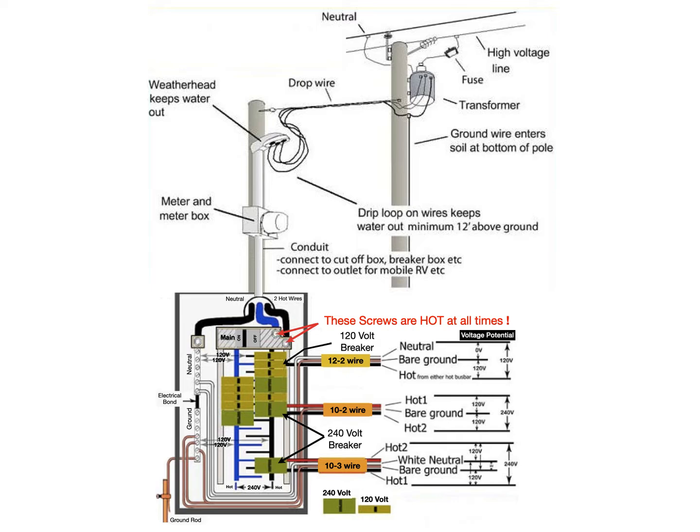The service connection enters the panel via the main disconnect breaker, which is utilized to isolate the complete home by stopping all electrical power flow. This is positioned in between the service meter and the rest of the electrical panel. The main disconnect is a circuit breaker housed in the electrical panel. In order for this to work, the circuit breaker must be in series with the 2 hot line conductors, because it must cut power to all circuits. It is rated to be able to interrupt the total household load.